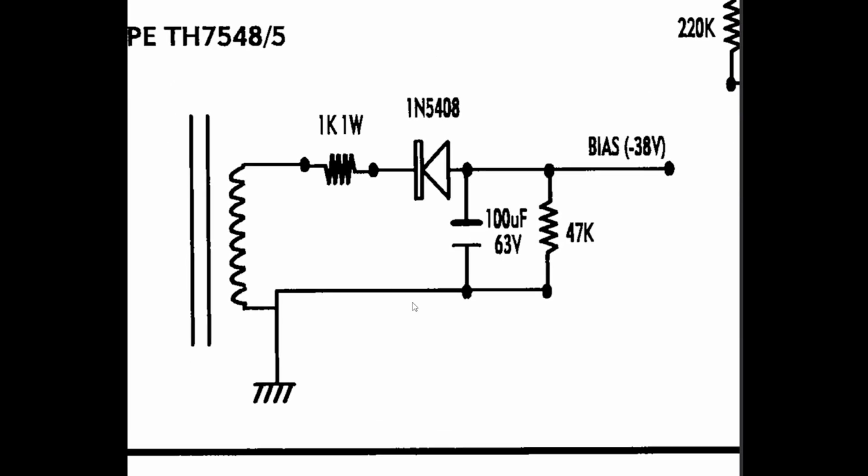Okay, so in this amp, we're going to have roughly 50 volts AC at this point. Now, because that's AC, it's going to go above and below zero at 60 hertz. So on the positive half of that, right here, we're going to have positive here, negative there. On the negative half, we will have negative here, positive there. So that creates two different situations for what's going on.